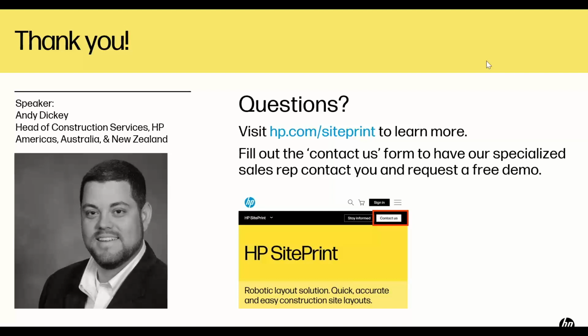Which total stations is SitePrint compatible with? Yeah, that's a great question. So we have 3 total station partners, Trimble, Topcon, and Leica. I'll just take them one by one. We're compatible with the Trimble RTS 573, the Topcon LN150, and there are 3 in the Leica bucket. The first one is the TS16, which is more of a survey instrument, and then 2 construction layout instruments, the Icon 70 and the Icon 80.